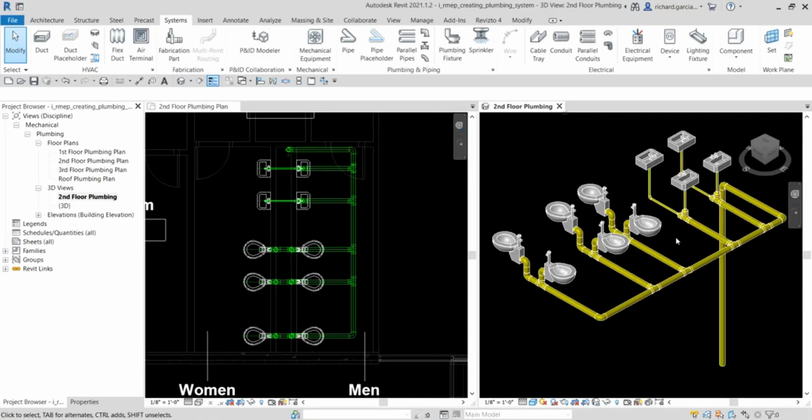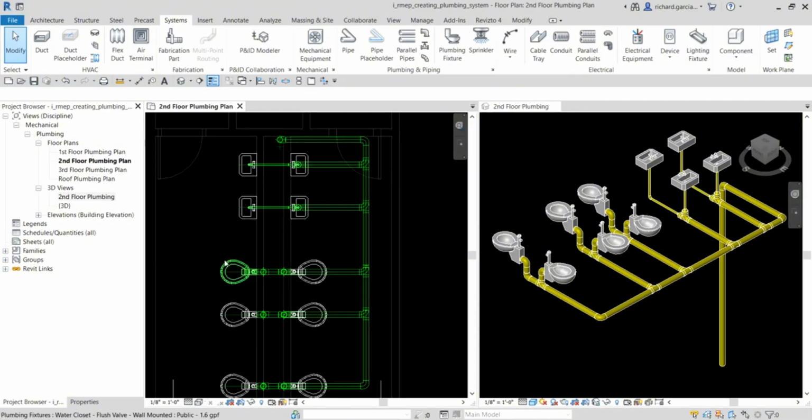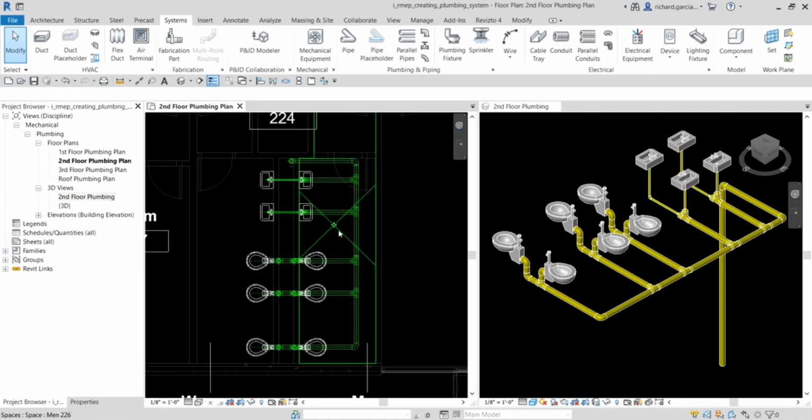Now the next thing that we are going to do is, let's say you want to create a gray sanitary water system layout. Let's say you want to recycle the water. So you do not want your lavatories here to be connected along the sanitary with our water closet. So I'm going to create a gray sanitary water system. How to do that? You just need to edit your piping here.